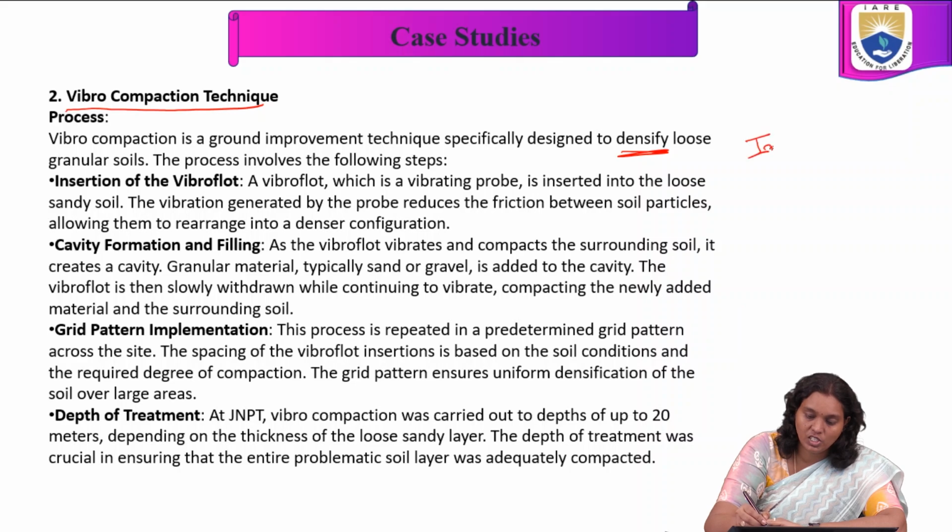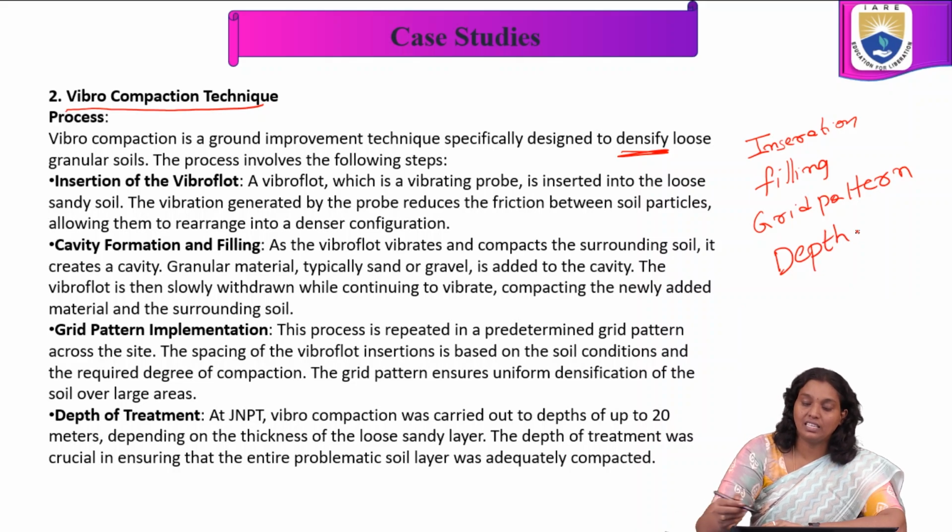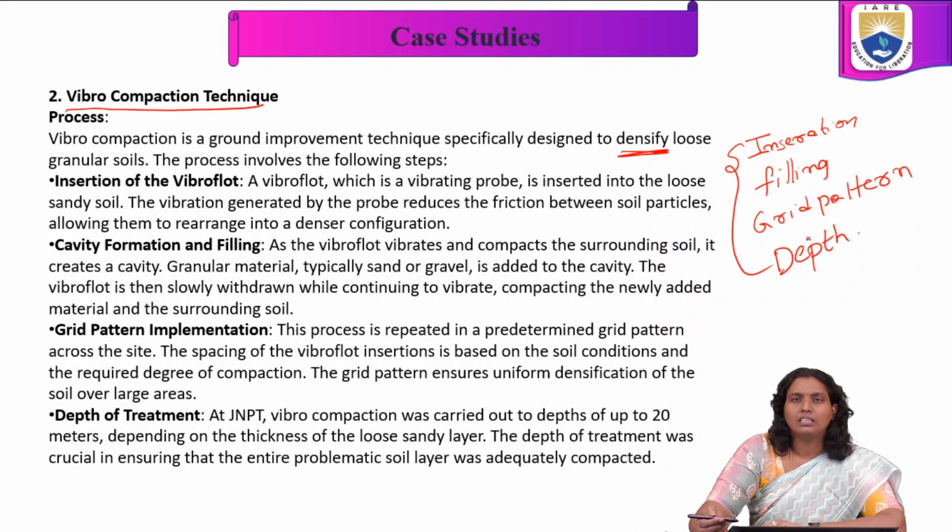The first is insertion, and the next is filling, insertion after filling. Next, what kind of grid pattern we are choosing, and depth: till how much depth the treatment will be done. These are the steps involved in the vibro compaction technique.